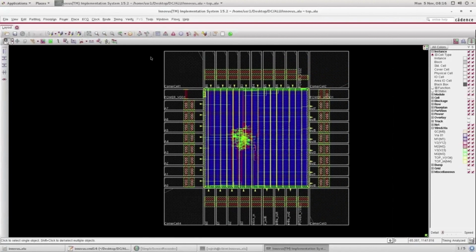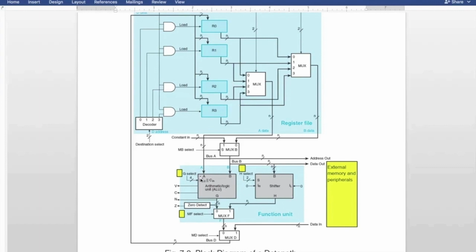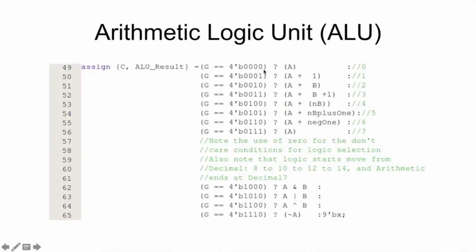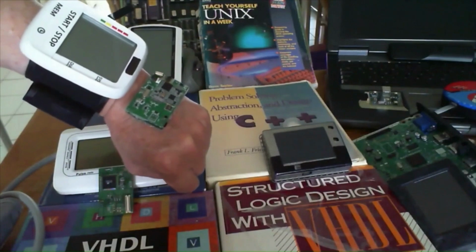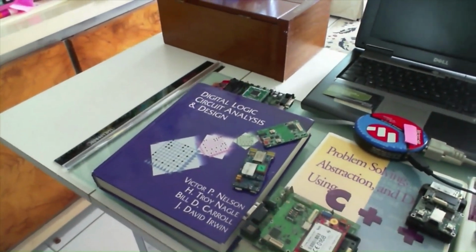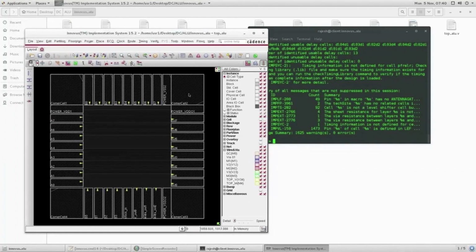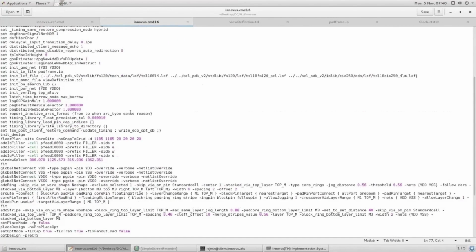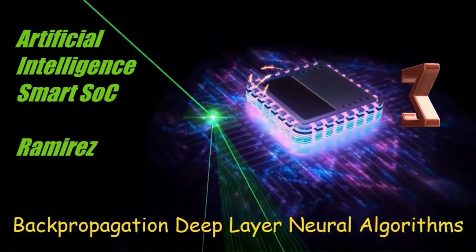High clock speeds and long, narrow wires can result in a reliability problem known as electromigration. Over time, the movement of electrons can move the metal atoms and result in a break in the wire. So we want to fine-tune the wires for some nets, such as clocks, and keep these wires fixed through multiple passes of engineering changes. At the end of routing, all new wire segments are assigned to a user-specified group. The routing program makes sure that nets routed in one iteration do not prevent the remaining nets from being completed.